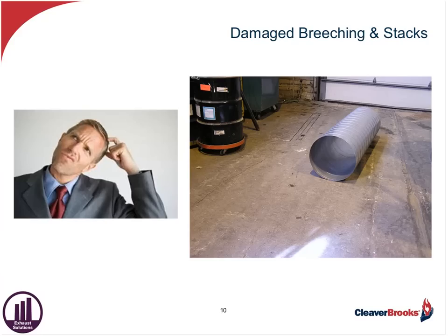If we use the wrong material for the stack itself, this can lead to some serious problems, not just in terms of repair, but downtime. I can't tell you the number of instances that I've seen carbon steel breeching and stack being used for boilers that get into very, very close condensing situations and have some real problems as a result. So when that's got to be replaced, various sections have to be replaced. Obviously, the boiler is down, and if you don't have standby, your production also is impeded. So downtime becomes a real problem, and it can be directly associated with stacks.